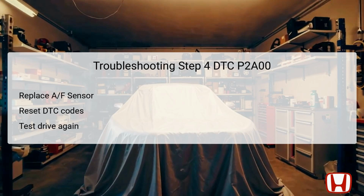After resetting, it's crucial to perform another test drive while monitoring the vehicle's performance and the HDS readings to verify that DTC P2A00 does not reappear. Successfully replacing the sensor should restore normal operation, as the new component will provide accurate readings for the PCM. This step confirms the resolution of the issue while ensuring the vehicle's efficiency and compliance with emission standards.